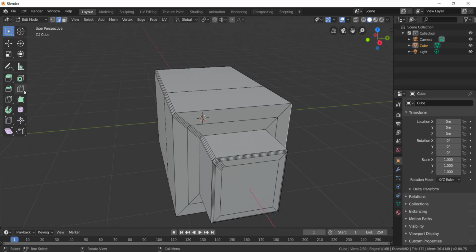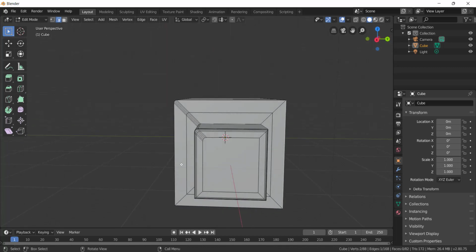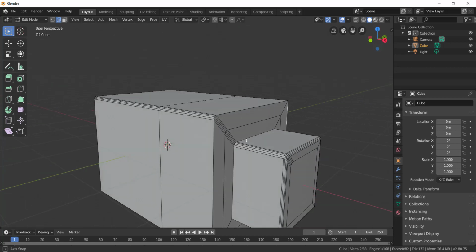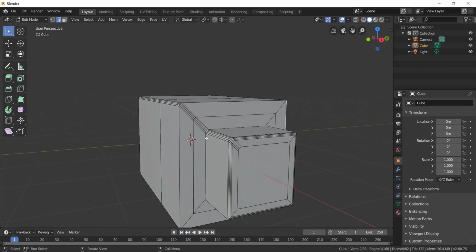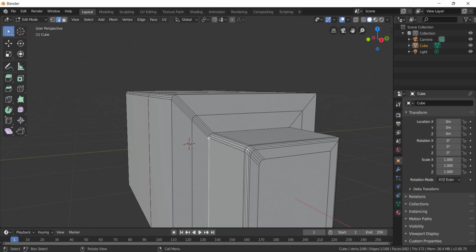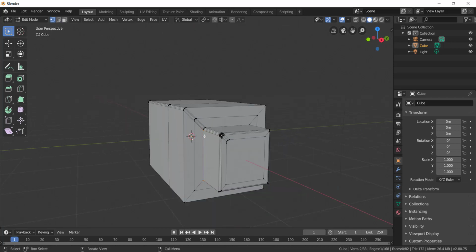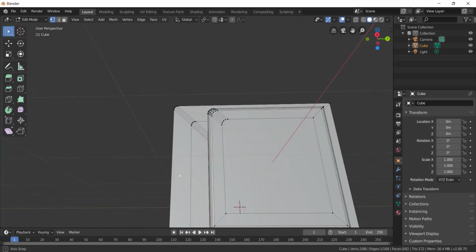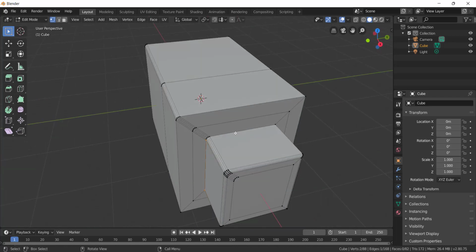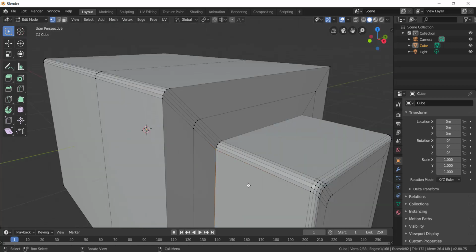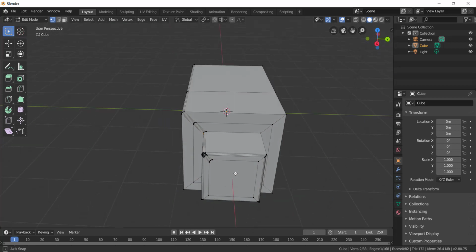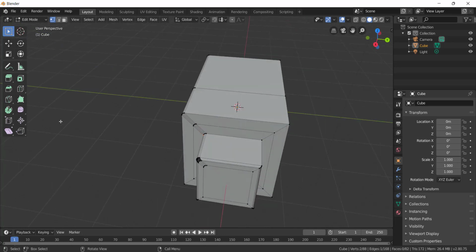And after that we have the loop cut. Loop cut is nothing but adding extra edges, adding a loop. So this is a loop. See, this line starts here, this vertex, or this edge starts here. Think it is starting here and going around the box and coming here, and it is ending here, right? So this is a loop. It is a complete loop, and you can take loops using loop cut.